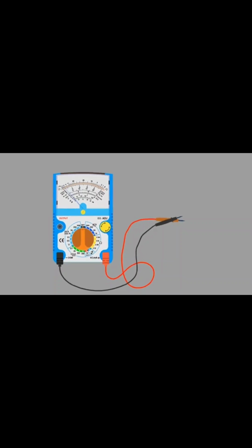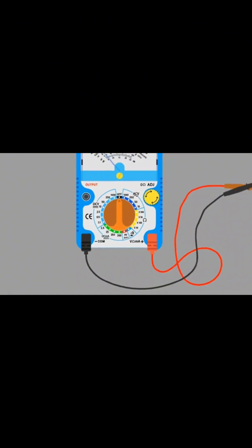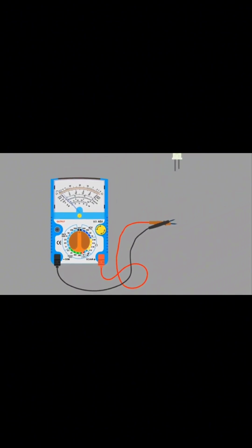How to measure DC current with an analog multimeter. Take an analog multimeter. Connect the black probe with the common port. Connect the red probe with the positive port. The blinking line shows the DC current section. The arrow shows the measuring range of DC current. Take an LED and use it as a load. The longer terminal is positive and the shorter terminal is negative. Take a phone battery and use it as a power source.